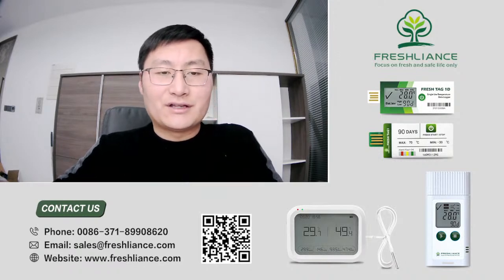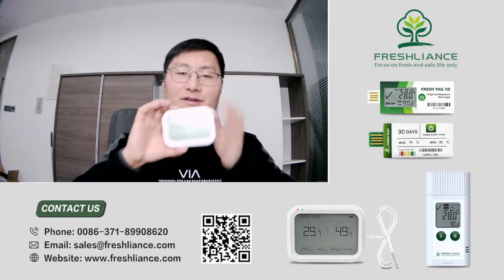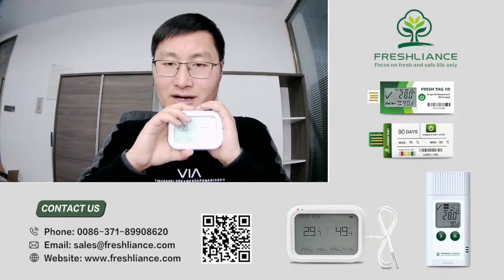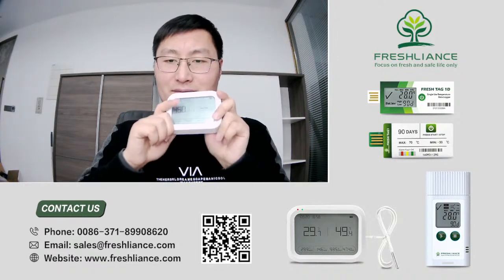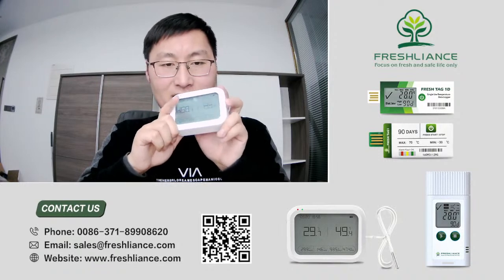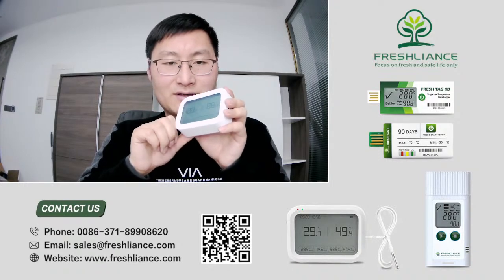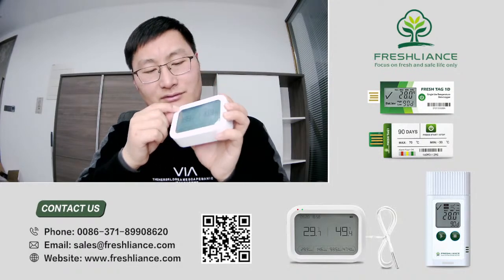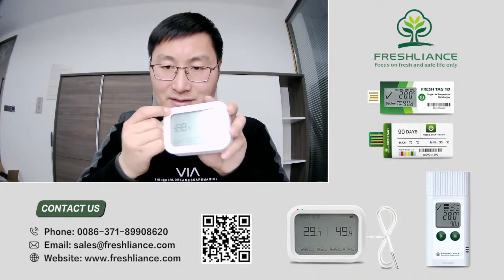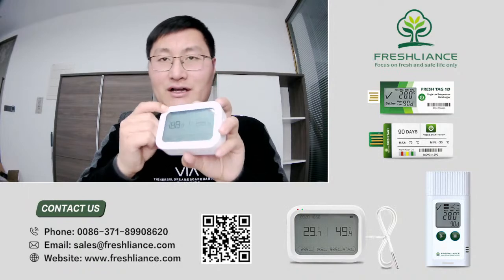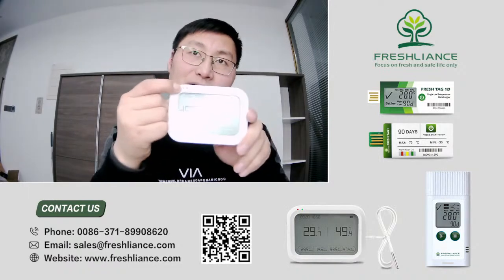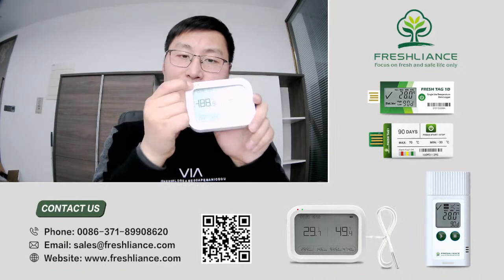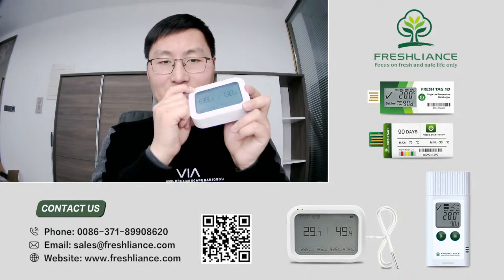At monitoring status, when the temperature is out of alarm range, the red LED flashes 3 times every 15 seconds, and the buzzer alarms 3 times every 1 minute. So there are two LED lights. They are very small, but when they give light, you will see it very apparently.